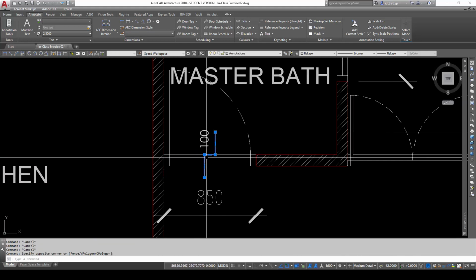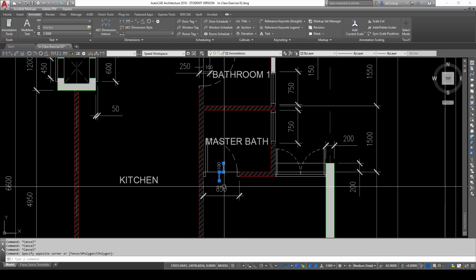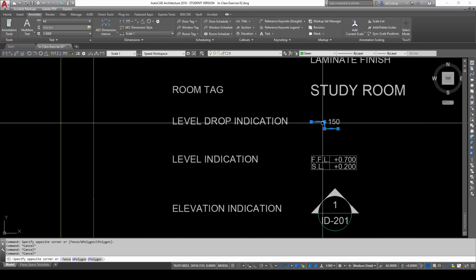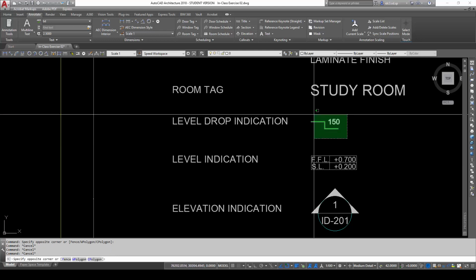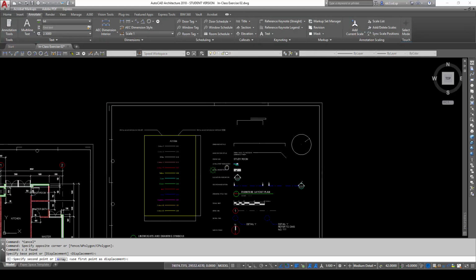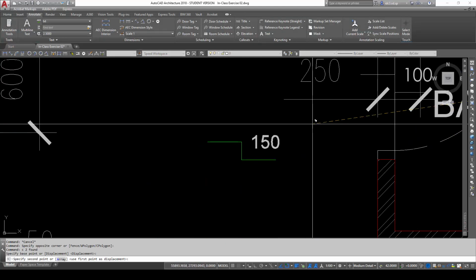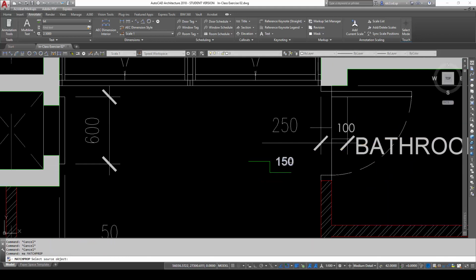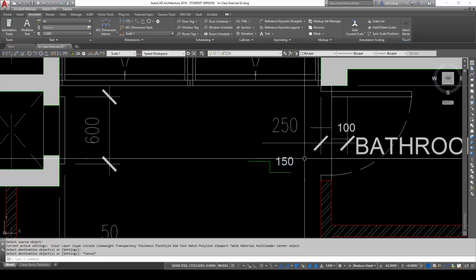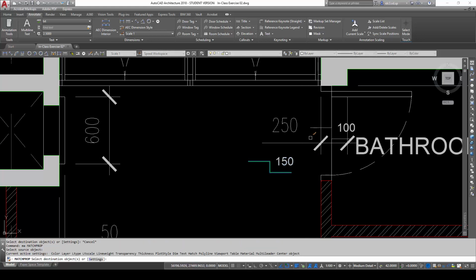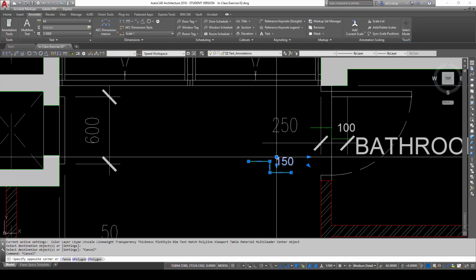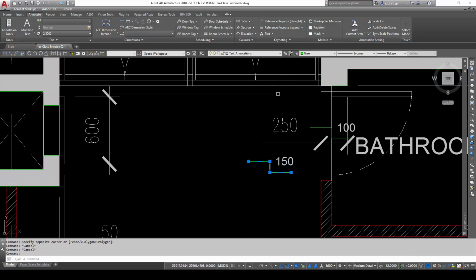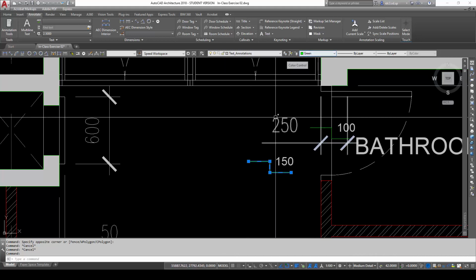Now the floor drops themselves are a little bit tricky, because inside here there is a symbol for this. So we can simply copy this one first over here. This floor drop symbol, we can simply match property the text and then match property the line. Why is this particularly in text annotations, yet still green in color?